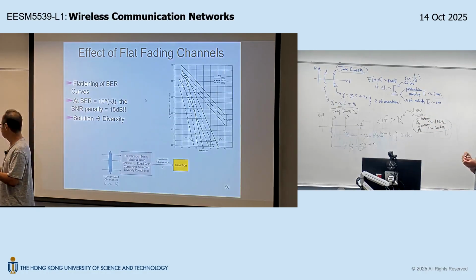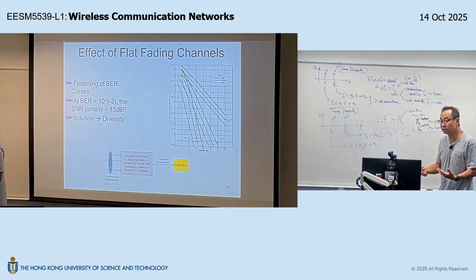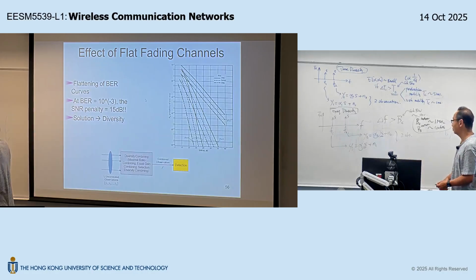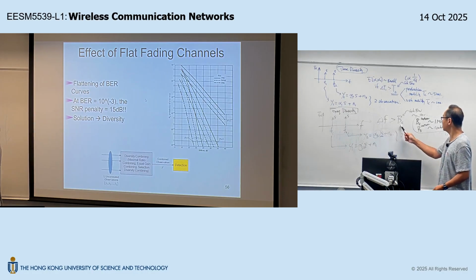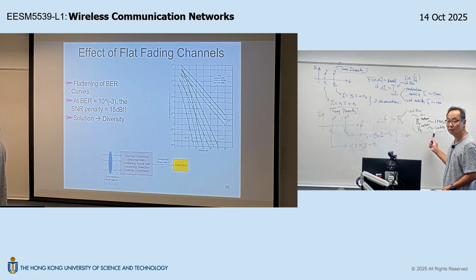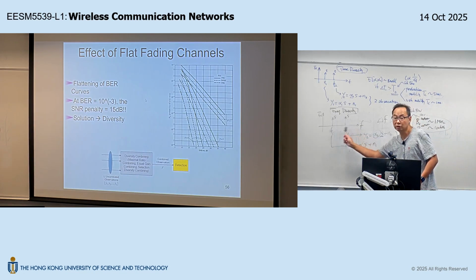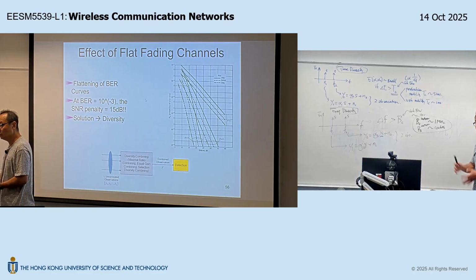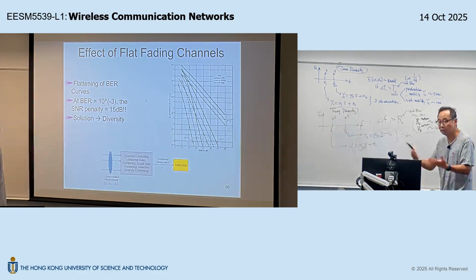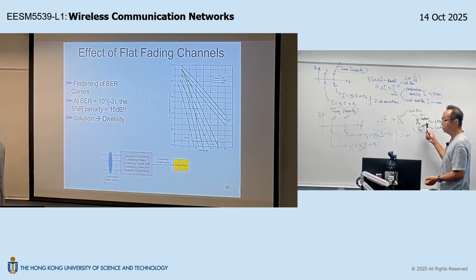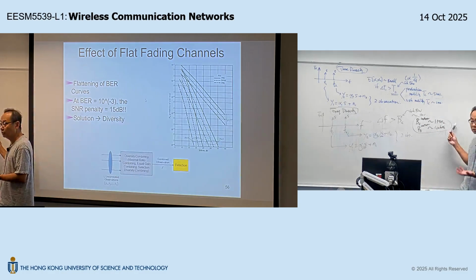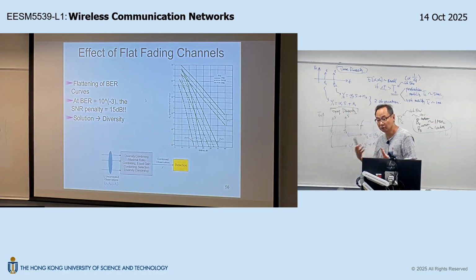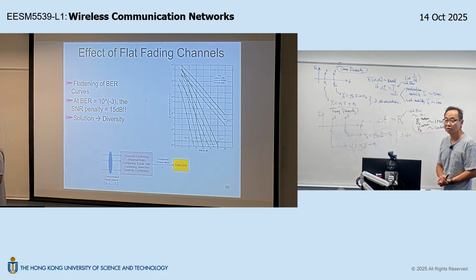So that means if this system is designed to operate in outdoor, like GSM system, like 3G, then the coherence bandwidth we are talking about is only 100 kilohertz. And that means this frequency separation just needs to be around 100 kilohertz, and that would be sufficient. If this system is designed for indoor, like Wi-Fi, then this coherence bandwidth would be 10 times more, like megahertz order. And that means this frequency separation needs to be at least megahertz separation. Is that okay?